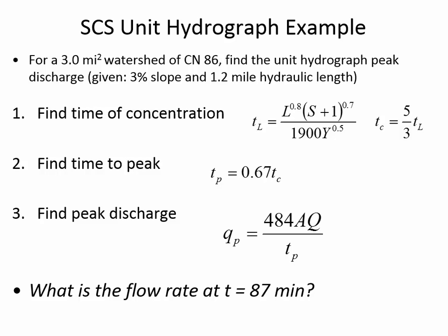And this is only in traditional units. You know, these curve numbers, the tables that you can look up for curve numbers are anticipating that you'll put it into this formula, and then what you end up with is inches. So 1,000 divided by 86 minus 10, that gives us a storage of 1.63 inches.